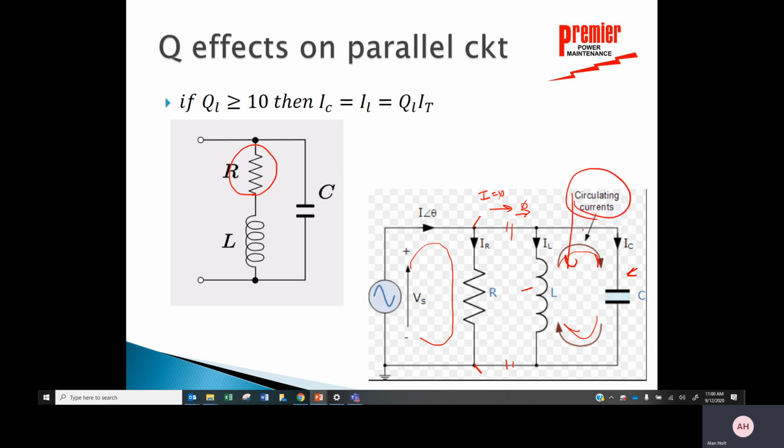To the point that at a hospital here in Indianapolis, they had a lot of inductors. They are called chillers inside the plant, for cooling and airflow and everything else. Their power factor was horrible. So they added this large capacitor bank at the utility. So here's the utility right here.